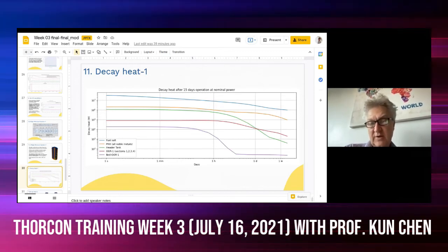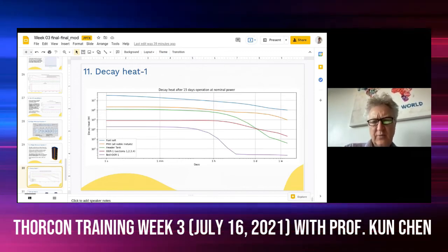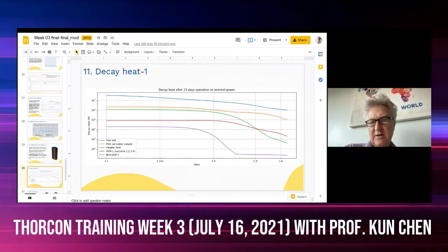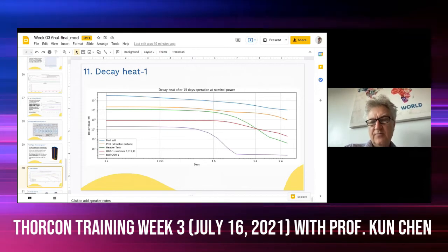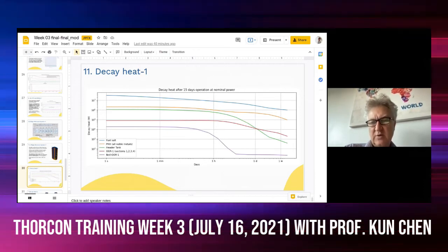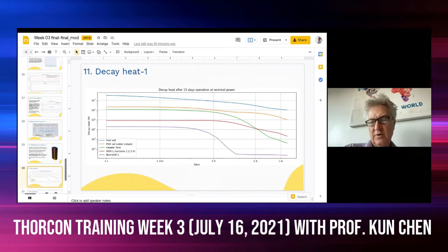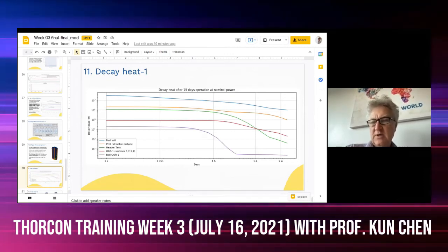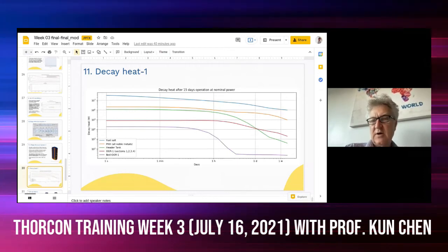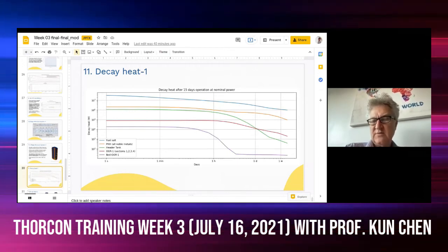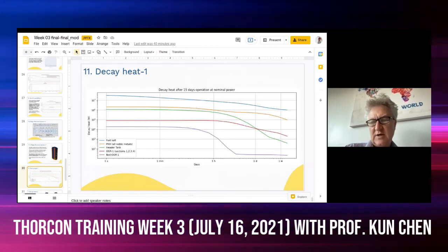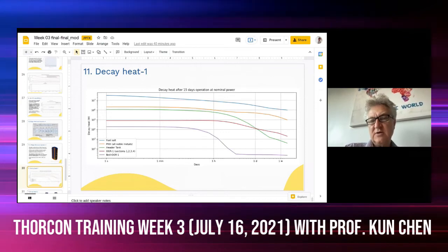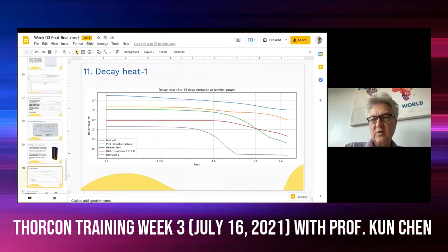So that's load following. Startup would be, you start with no fuel salt in the drain tank or the primary loop. You want to have your shutdown rods lowered and then start filling it with fuel. The fuel should be targeted to be slightly under critical conditions when it is flowing. So you have the shutdown rods in place, you start the flow, and then you start gradually removing the shutdown rods.